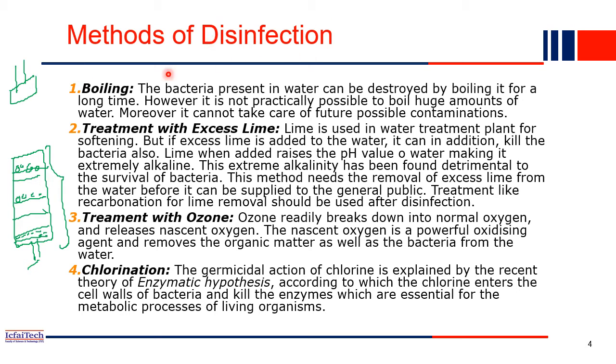So these are different methods of disinfection. The first is boiling. Boiling is possible on a small scale for house purposes, where we can use the boiling technique as a disinfection. But for urban cities like Hyderabad or any municipal corporations, the water demand is very high, so boiling is not a practical solution for large cities. The bacteria present in the water can be destroyed by boiling it for a long time.